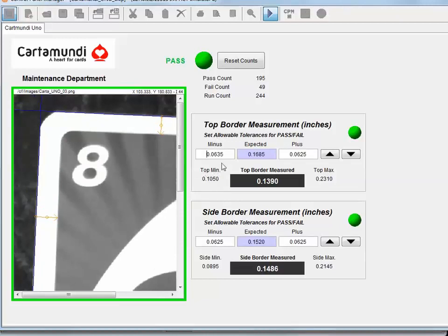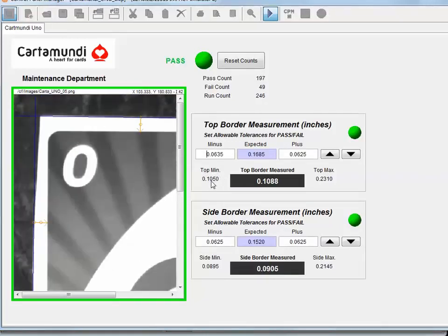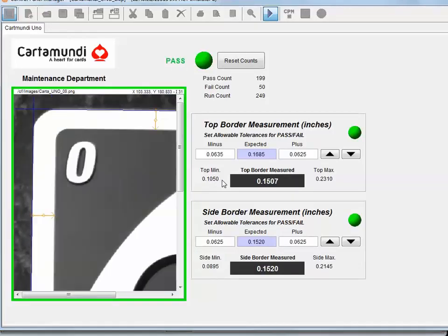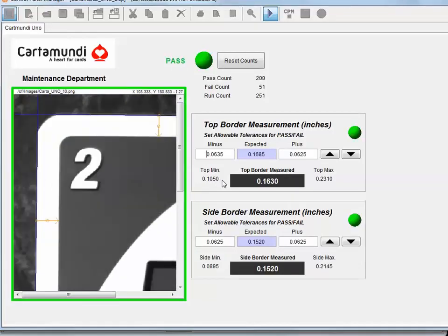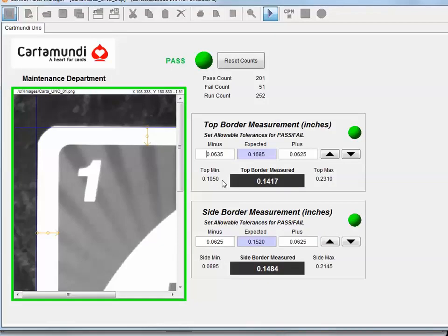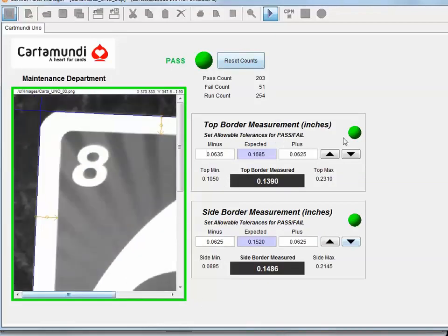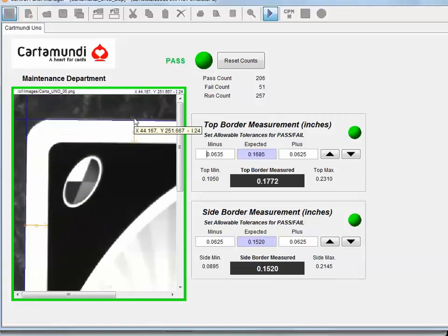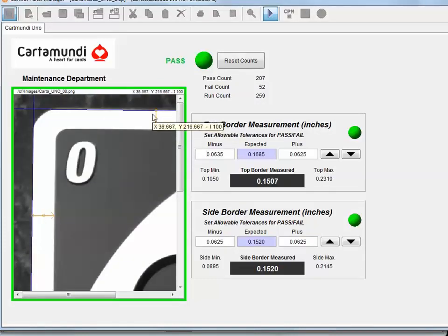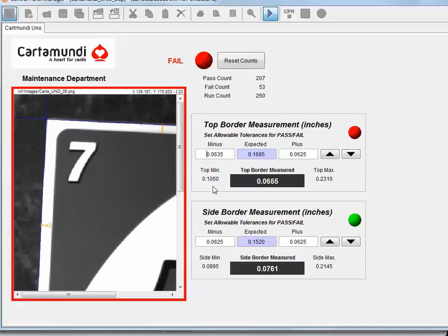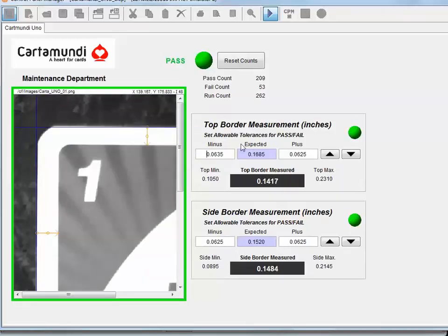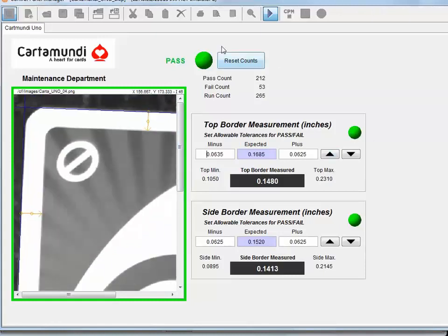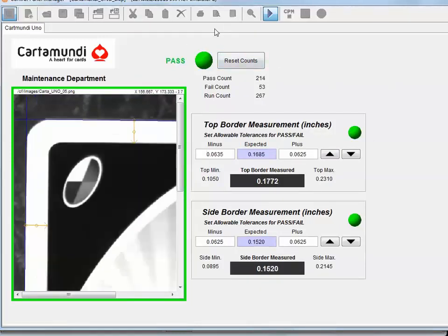This is the actual raw data. This is the engineering value in inches. I did a conversion in the Vision Program Manager of pixels to inches, so everything we're seeing on here is actually displayed in inches. So for purposes of pass-fail, as these images click by, you're able to determine the length of this arrow, if it's long, if it's short. If it's outside the value of the tolerance band, then that individual tool will fail, which will lead to the overall fail in the top corner here.